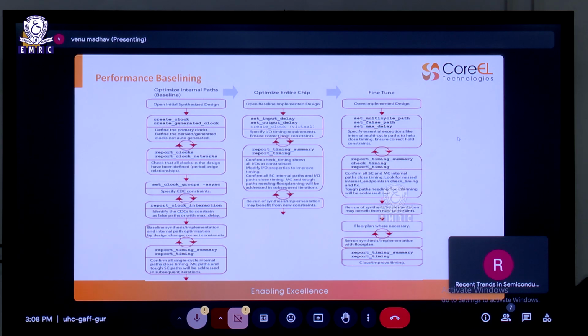Global clock buffers are there. BUFG is global clock buffer. There are 12 different buffers there. Vertical and horizontal buffers are dividing my complete circuitry, complete silicon into 12 different regions. It will divide the FPGA into clock regions.